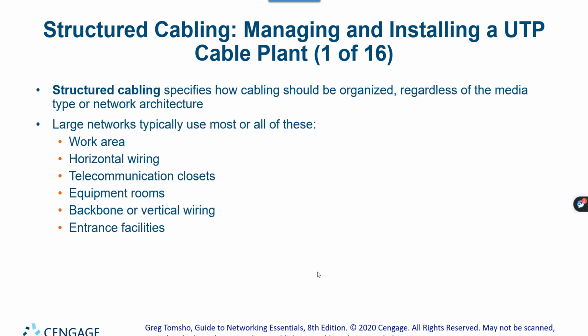The fear is that if you put them in the same wire tray or conduit, that the 120 volts or 110 volts is going to jump from the power system to the networking equipment. So we have all kinds of rules about where we can run this cabling. And if you run it in the wrong place, then the inspector is going to come by and he's not going to allow you to let people in the building because it's not done correctly.